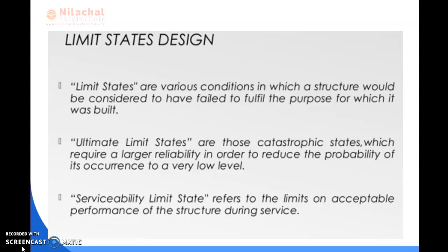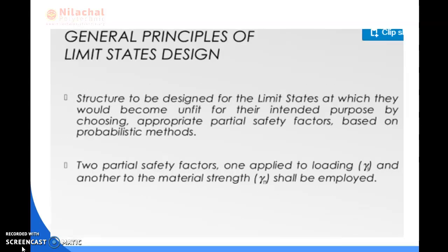In the ultimate limit state, we consider reliability and the probability of occurrence. In the serviceability limit state, we consider the performance of the structure during the service period. Every structure has a particular service period.